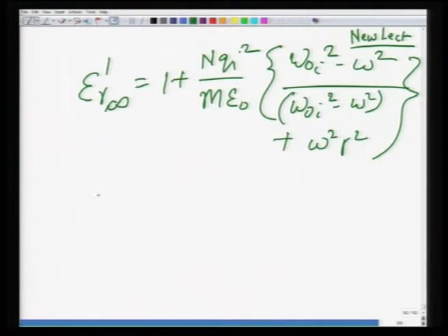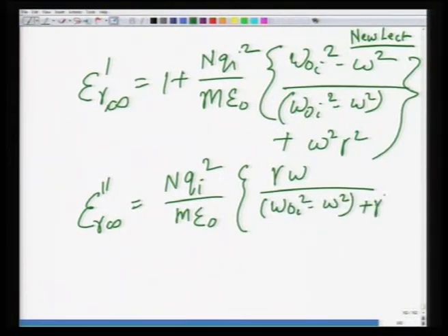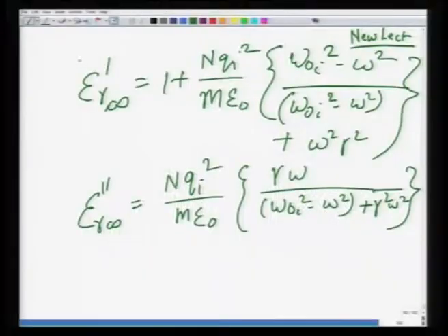So, this was following the consideration that we were doing analysis for a charged dipole, assuming it to be a linear mechanically oscillating oscillator, and we worked around with the equation of motion to reach this expression, which is the frequency dependent expression for dielectric response specific to electronic and ionic mechanisms. So, you have this frequency dependence of dielectric constants.